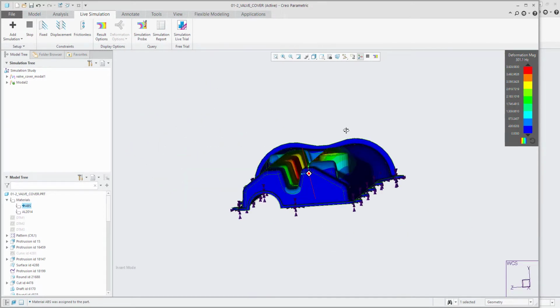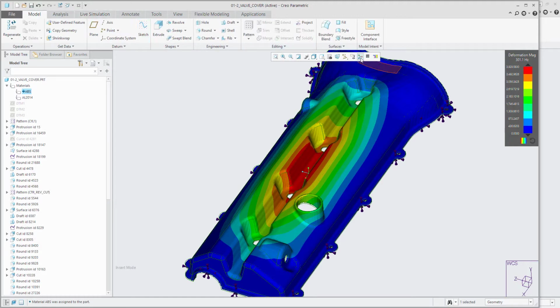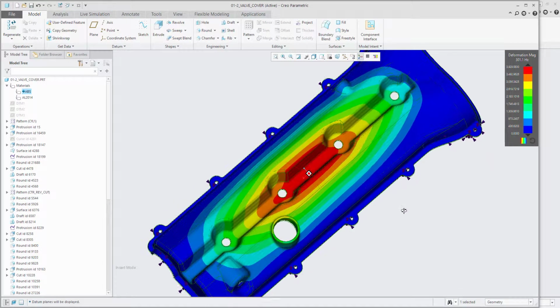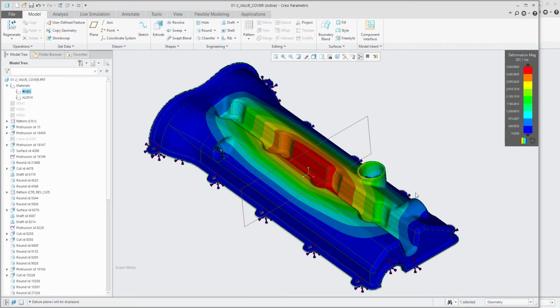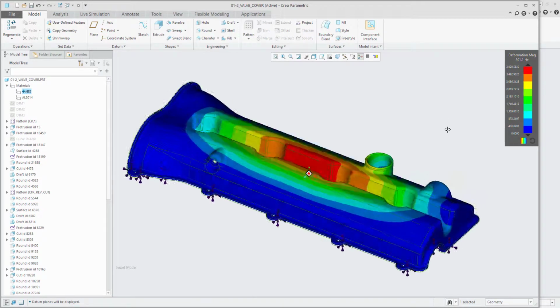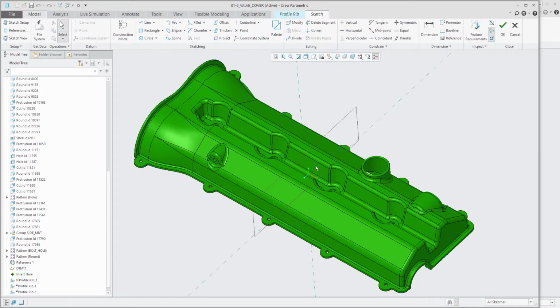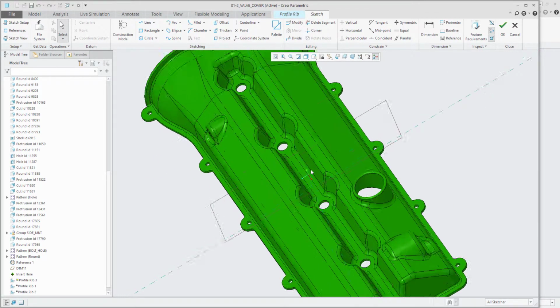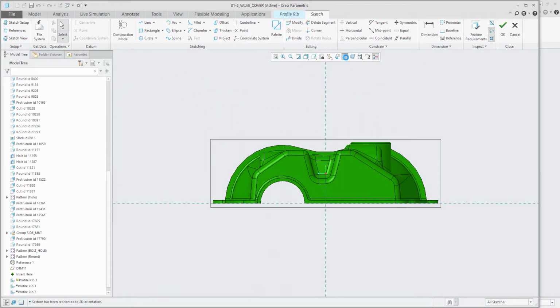So what I can now do is have a look at what sorts of design tricks I can play to try and modify this existing design, because I don't really want to have to design the whole thing again from scratch. So perhaps one thing I can do is to put a rib at this top here, because I could see that it was breathing, kind of splitting apart. So if I put a rib in there somewhere, then maybe that would be appropriate.